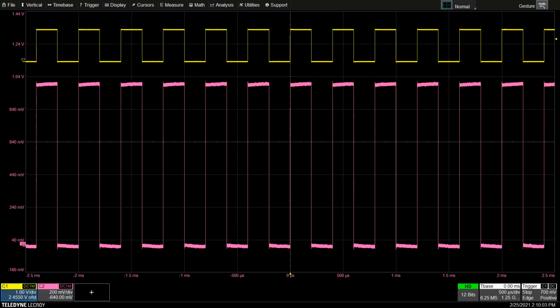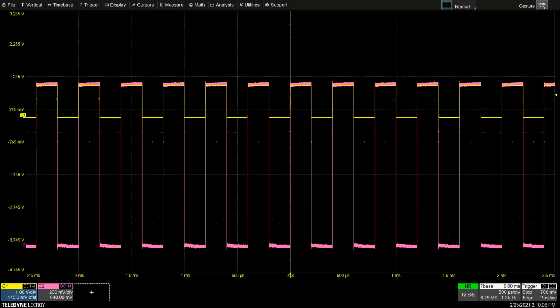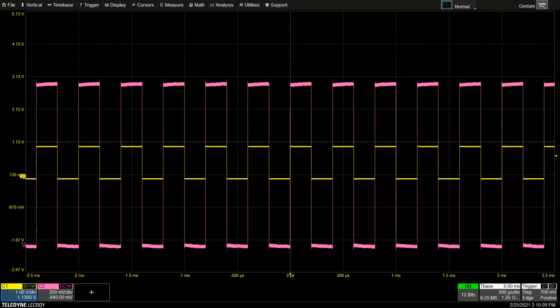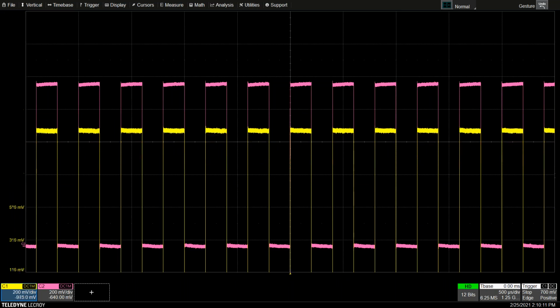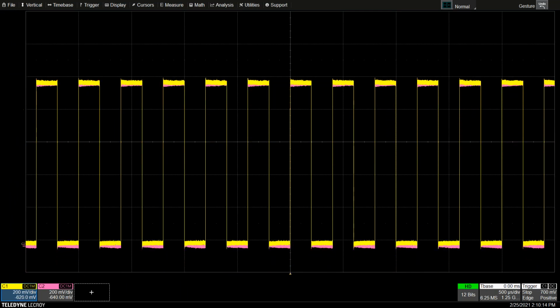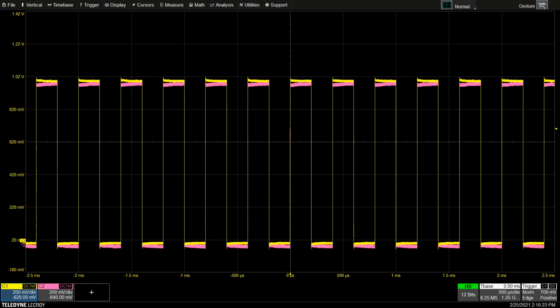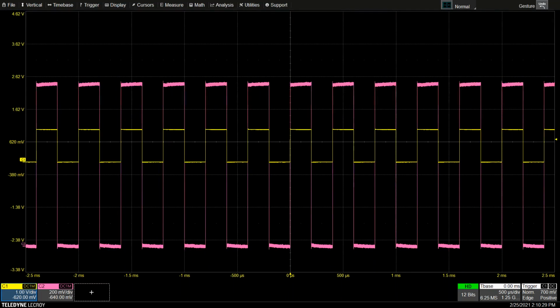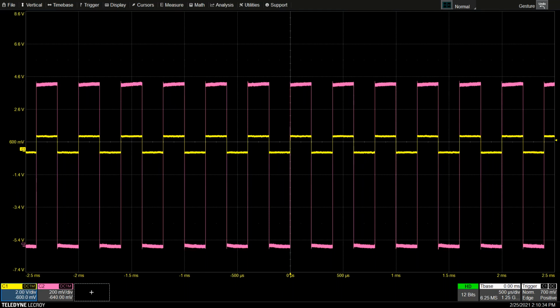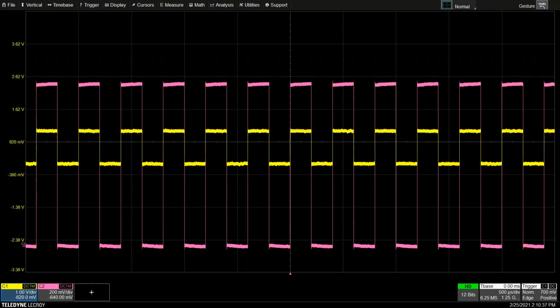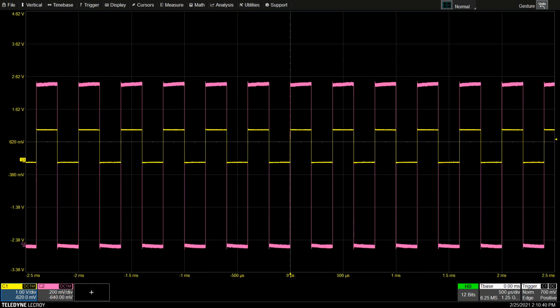So let's do this. Let's touch channel 1, bring it down here, and let's increase using the vertical zoom. Let's get to the same time scale. And when we look at that, let me bring this back down. Okay, so there's the 1 volt per div. And just to make it really obvious, I'm just shrinking it down a little bit more. I've got some noise in here, looks like from something. There we go. And let's just stop the scope.